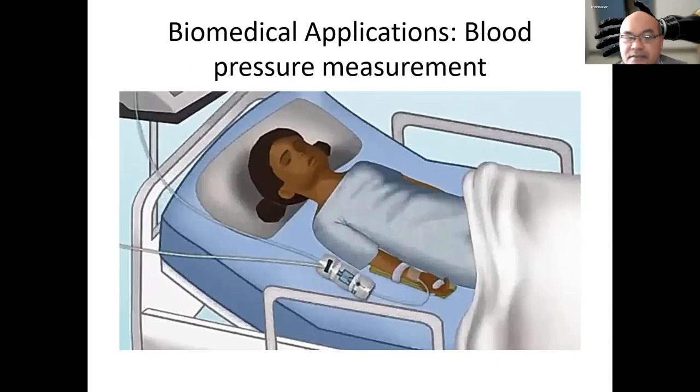In this particular case that the doctor is mentioning, the calibration is done against the atmospheric pressure. So the 0 in this sensor means that the blood pressure is the same as the atmospheric pressure, at 1 atmosphere, or 10 to the power of 5 Pascal.